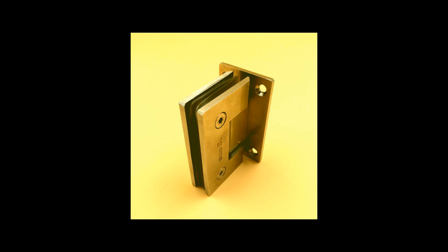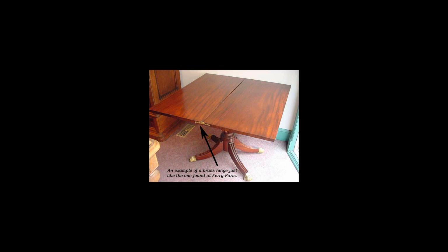Drop leaf table hinge. Mounted under the surface of a table with leaves that drop down. They are most commonly used with rule joints. Piano hinge. A long hinge. Originally used for piano lids, but now used in many other applications where a long hinge is needed. Living hinge. A hinge consisting of material that flexes.